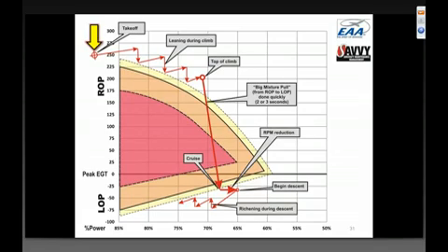We'll start with takeoff. We take off at basically 100% power, assuming the airport is close to sea level, and we take off with a full rich mixture, which in a typical airplane is something like 250 degrees rich of peak, very rich mixture. And then we start to climb.